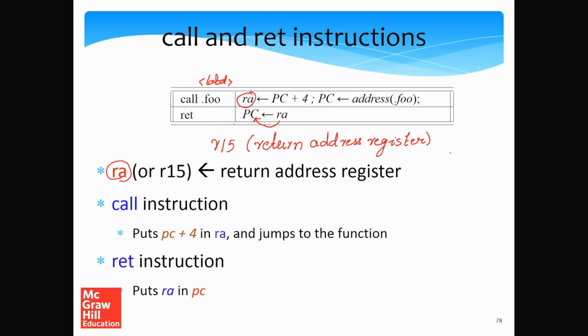In our register file that contains 16 registers, the last two registers, namely R14 and R15, are reserved for special purposes. R14 will be the stack pointer and R15 is the return address register. All the other registers can be used by the program. Here again there is some amount of semantics that different instruction sets typically define.